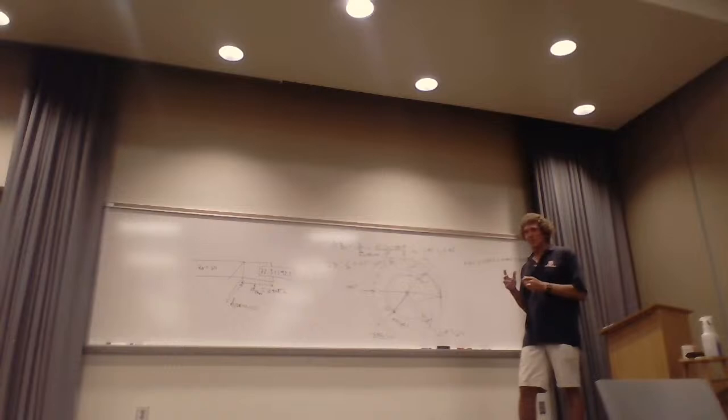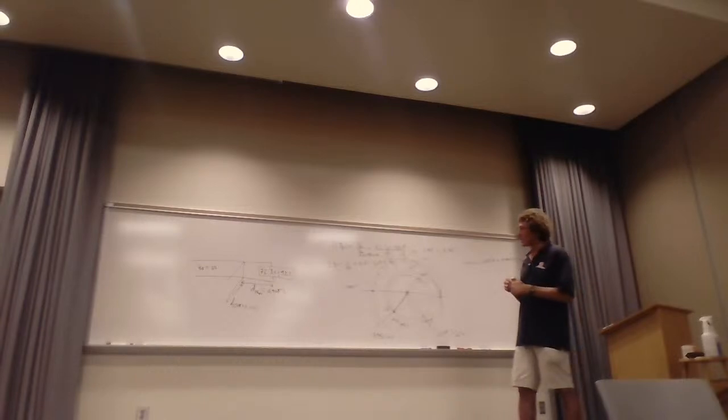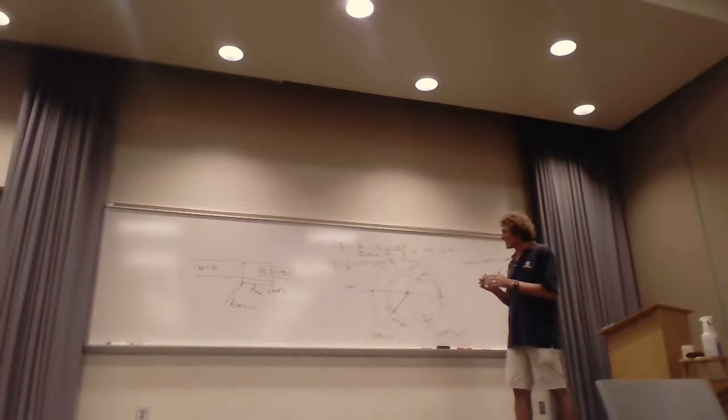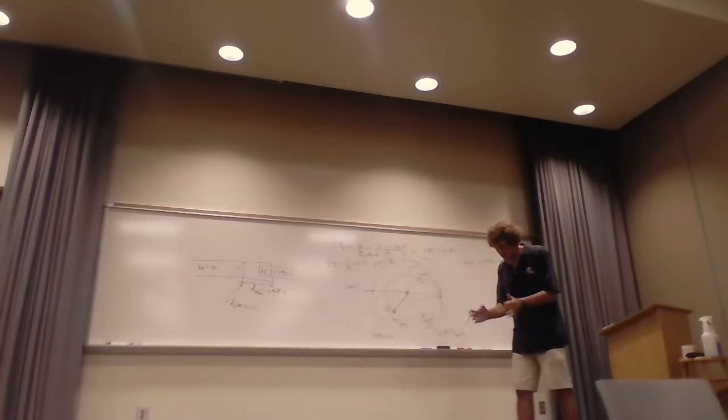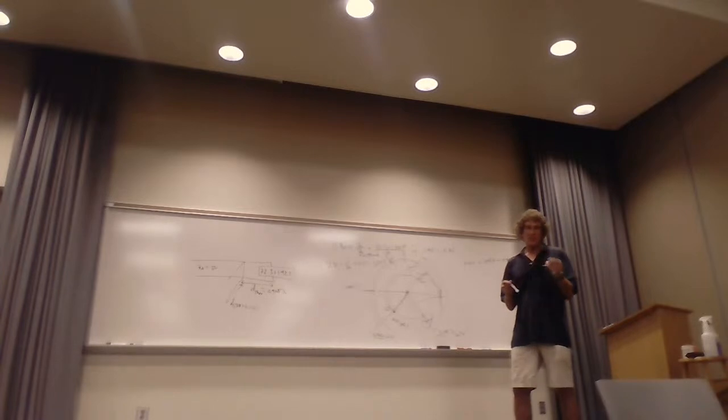And a lot of people, you know, they need a little refreshing on that, so this is a good problem to do it. Y'all with me on this, on how you do it? Nothing tricky at all, but you have to have your head on straight when you're doing this stuff. You got to make sure I'm in the admittance domain. Admittance is 1 over impedance. Everything's in parallel. If it was a series stub, then I'd be in the impedance domain.